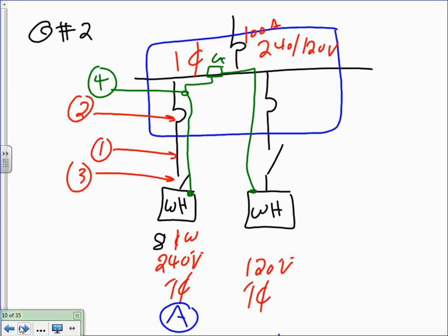All I need you to do, guys, is find it for the 8 kW. I care less about the second one. I just want the 8 kW information. Here's my 8 kW, 240 single phase. The system is 240/120. We need to size first the conductor, second the overcurrent protection device, third the disconnect, fourth the equipment grounding conductor. Four things for this one.